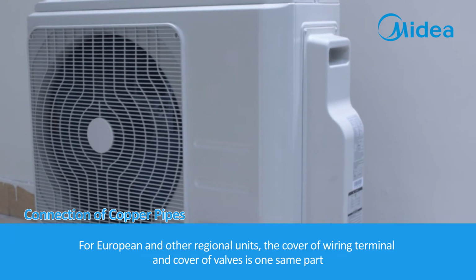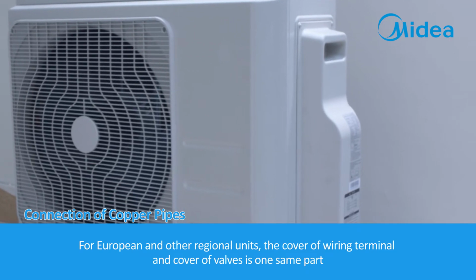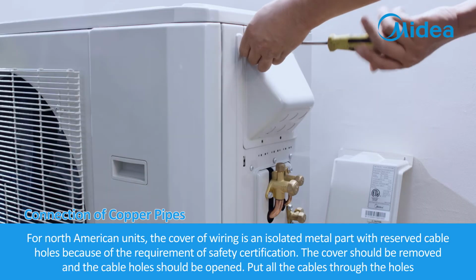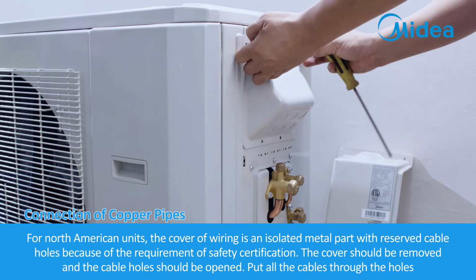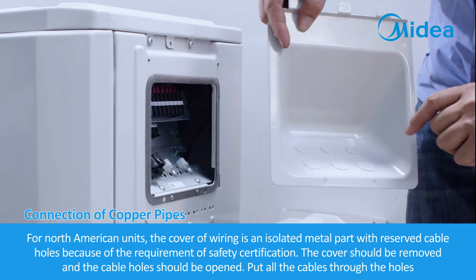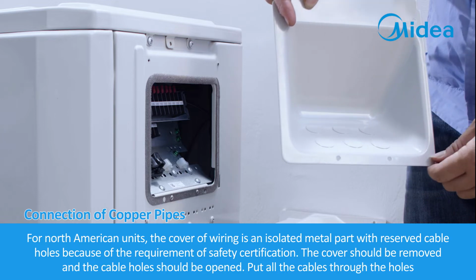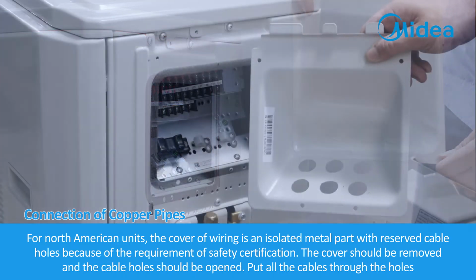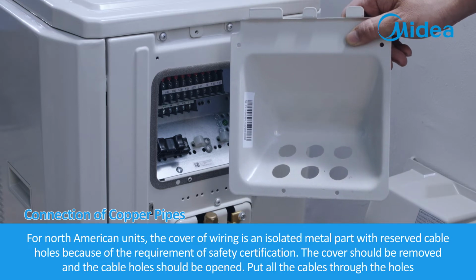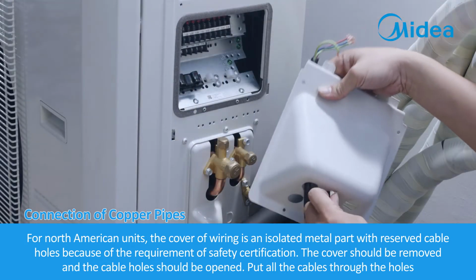Wiring. For European and other regional units, the cover of wiring terminal and cover of valves is one same part. For North American units, the cover of wiring is an isolated metal part with reserved cable holes because of the requirement of safety certification. The cover should be removed and the cable holes should be opened. Put all the cables through the holes.